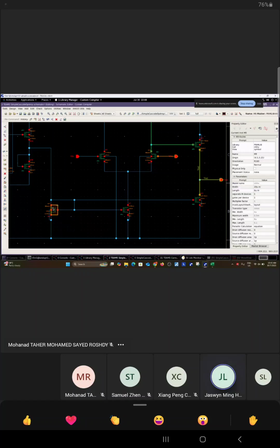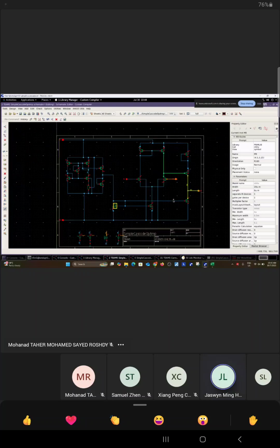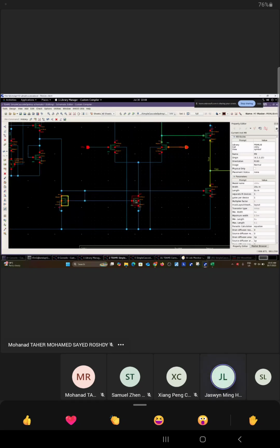Oh, because just now you showed me the output, the I out for the current bandgap is the one you get along this line, right? Yeah, it's 50 micro, right? Yeah. Then it gets multiplied by a lot here. I don't think we should multiply too much. I think you're going overboard with your current already. Yeah, let's try a different value here.